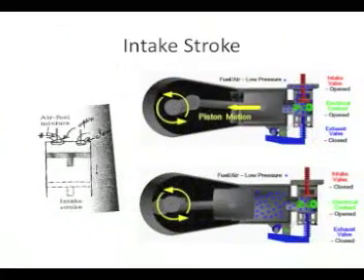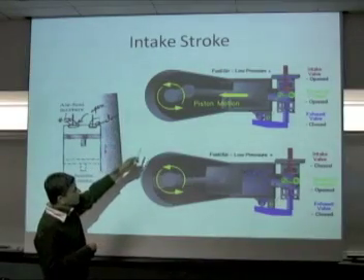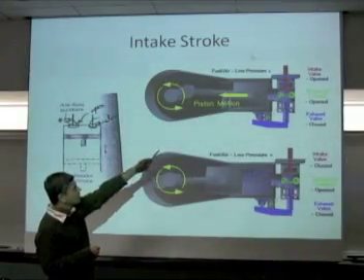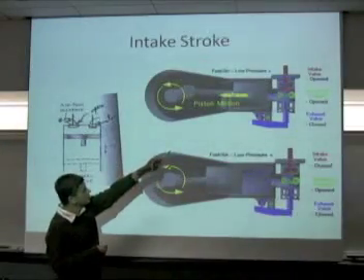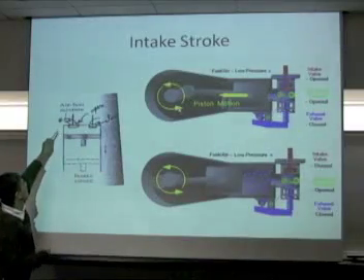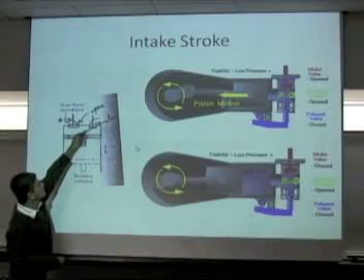Now let's look at the various features of the cycle. First, when the flow is coming in mixed with the fuel, you have the intake stroke, which is when the intake valve is open and the air rushes into the cylinder and pushes the piston down. As you can see, the air-fuel mixture is coming in, whereas the exhaust valve is closed.